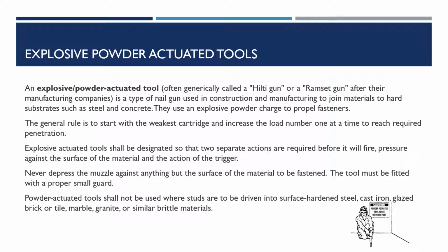Powder actuated tools shall not be used where studs are to be driven into surface hardened steel, cast iron, glazed brick or tile, marble, granite, or similar brittle materials.